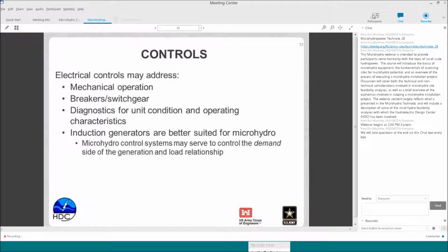With large-scale hydropower, the generation is synchronized with the grid. The power output of the powerhouses is determined by the load demands of the grid, but that output is controlled by turning the hydro unit on or off and then setting the hydro unit to run at a given output within the operating range, which in turn is controlled by a governor that throttles the flow of the turbine.